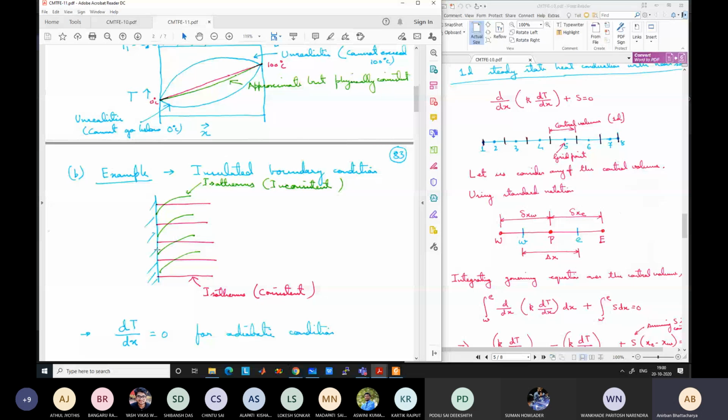Whenever one of my students shows me a result, saying, "Sir, I have run some simulation, can you check the result?", the first thing I check, if there is an adiabatic boundary condition, is whether the temperature profile at the boundary is perpendicular or not. If the temperature profile is not perpendicular at the adiabatic boundary, it means that something is wrong with the solution. So these are the checks that we have to do.